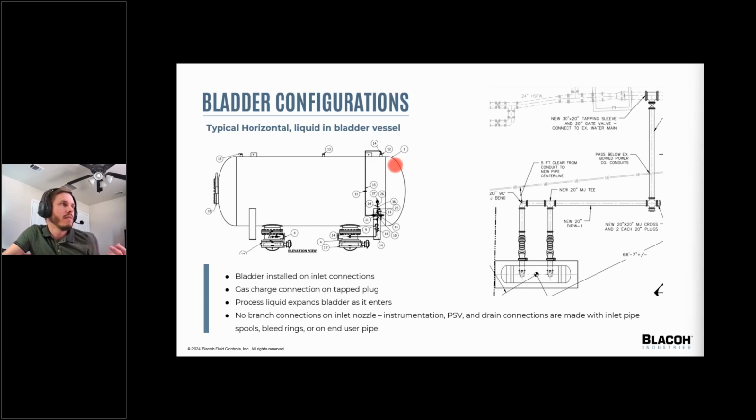Also, the vessel heads are typically forged in 12-inch diameter increments, here in the US at least. So from our experience, a lot of times at these length to diameter ratios it is cheaper to go with a smaller diameter vessel, even though it may be longer for the same volume. It can be cheaper than a large diameter vessel due to the more expensive and sometimes thicker heads.